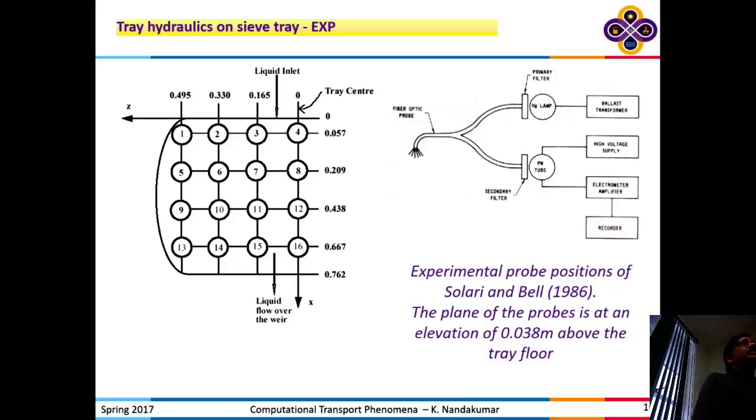It looks something like this. Okay? That instrument gives you the velocity at a particular point. But how big is that point? It depends on the size of the opening in the pitot tube. So it gives you an average velocity averaged over that size. Okay? But I can also measure the velocity by putting an orifice plate. What does the orifice plate do? It creates a pressure gradient in the same tube. By putting a manometer across this, you can measure what the pressure variation would be and convert that into a flow rate. That gives you an average flow rate over the entire cross-sectional area, because it gives you only average velocity. Okay? Whereas this gives you point velocity.